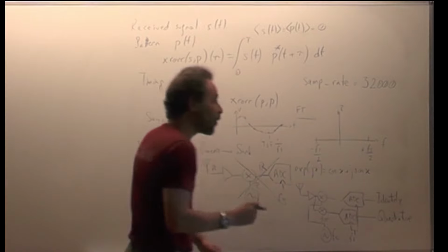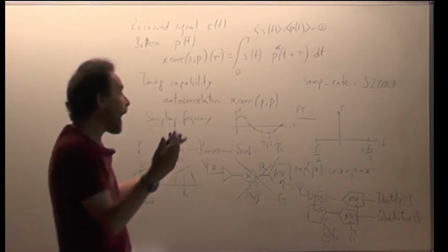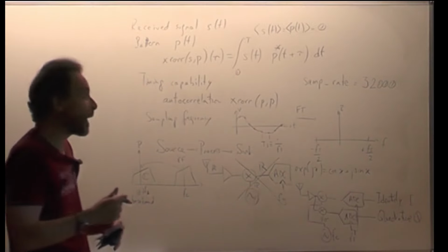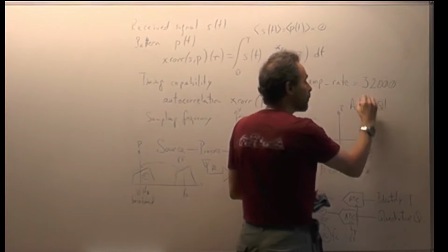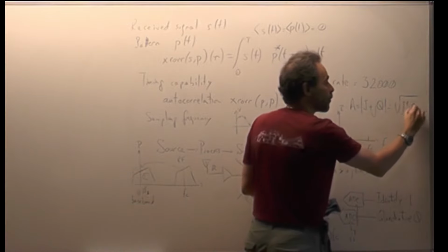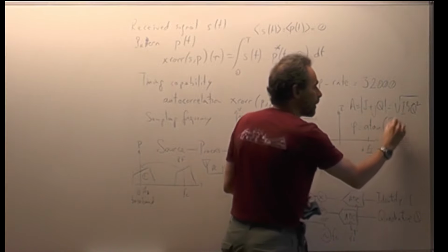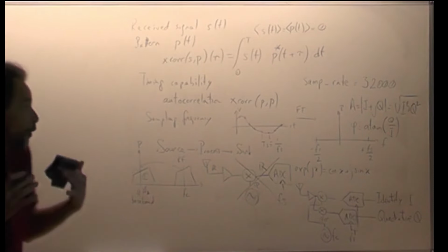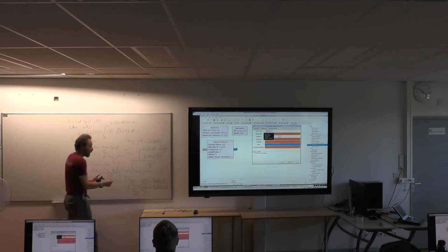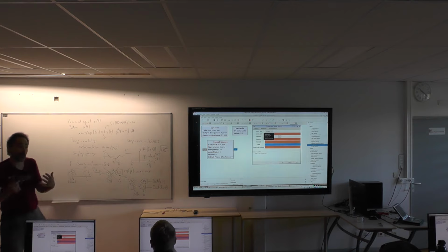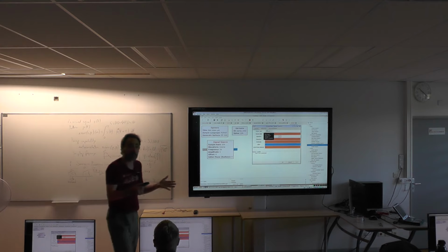So you have two components at the output of your software-defined radio receiver, which are I and Q. And I and Q match your usual complex quantity algebra, meaning that the magnitude of I plus jQ is the square root of I squared plus Q squared, and the phase is the arctangent of Q over I, as you would expect from complex algebra. So you see that naturally, whenever you're processing software-defined radio data sets, you will manipulate complex quantities most of the time and hardly ever real quantities, real in the sense of no imaginary part.